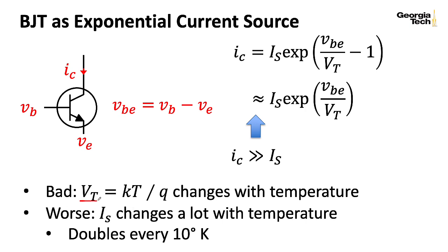Now, as far as the thermal voltage is concerned, you may or may not bother with dealing with that for a voltage-controlled filter, but you'll definitely have to deal with both of these if you're dealing with a voltage-controlled oscillator, because humans are exquisitely sensitive to variations in frequency, and you don't have to have a lot of musical talent or training to pick up on that. Everybody's going to hear it.